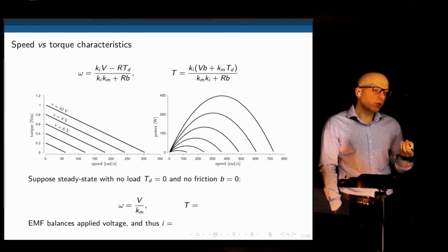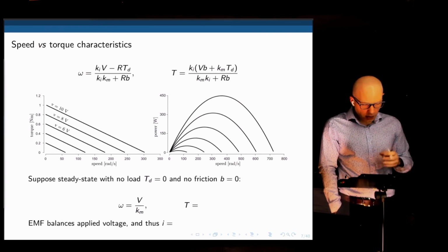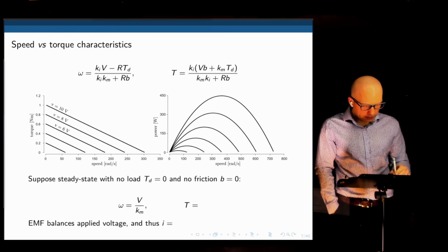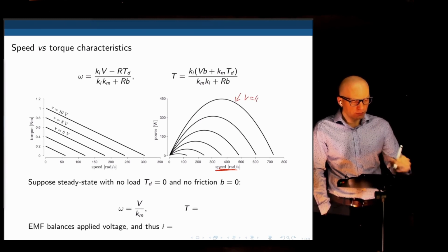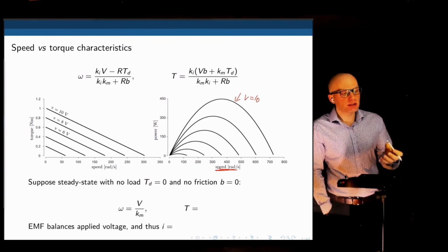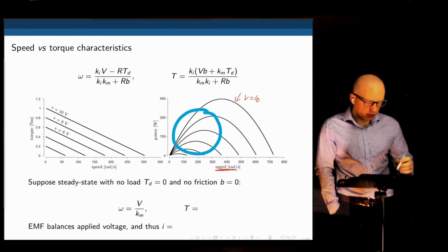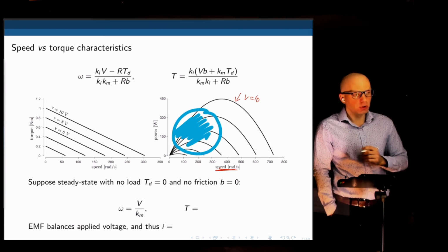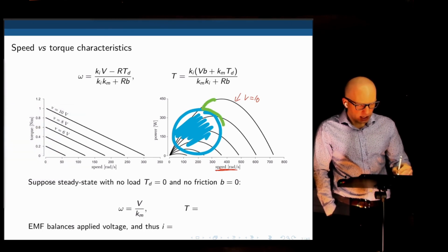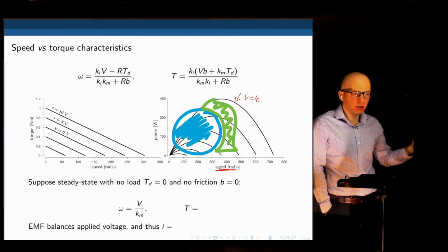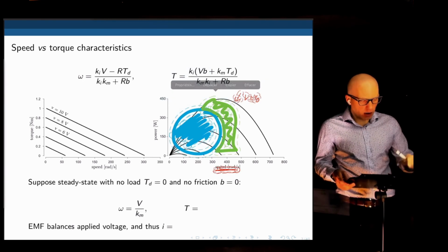That is to say that there are some operating ranges in this motor that the motor is designed to operate at, and there are some other ranges where the motor is not designed to operate at. If we now take torque and speed, multiply them, and create the mechanical power, and we plot that as a function of speed for different voltages, so each of these lines here is a voltage, this is what we see. And when you buy a motor, this is the sort of specification that we'll see in the data sheet. It's these two curves, and it will come with extra information saying that, for example, I'm just guessing, this is the nominal range of the motor. This is the range where the motor should be operating. And the data sheet, if you're buying a good motor, will further state that there is another range here that it can be used for a certain amount of time, but it's not the nominal operating range. Right? So these are the specifications that will come in a data sheet.